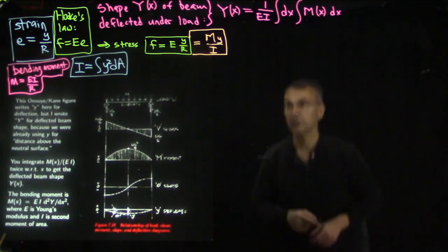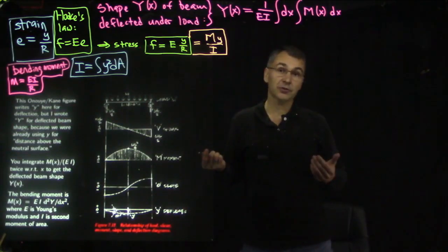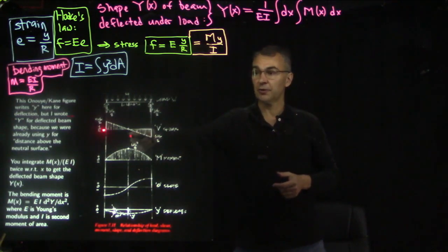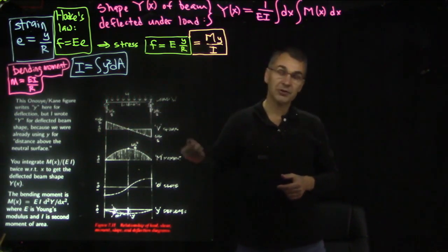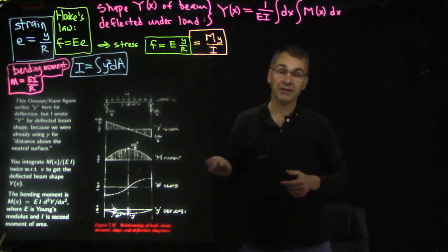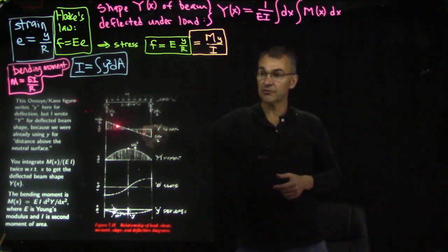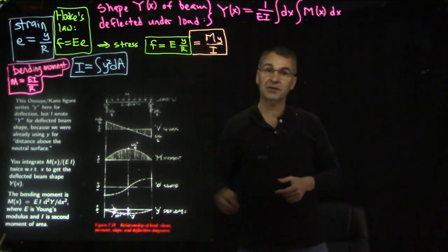If you have a distributed load, W, that is a downward load, and since this shear curve V is the cumulative sum, the running sum of all forces up minus down acting on the beam from 0 up to x, then you add up not W but minus W, since W is downward, we want up minus down to get V. So if you have some function W representing a distributed load, then the shear function V is the integral of minus W. So that's how this thing being positive gets you a negative slope here. Then the moment curve is the integral of the shear curve. And again, this is one of my favorite examples because this looks like the velocity vertically versus time, and this looks like the position vertically versus time of a ball thrown straight upward.